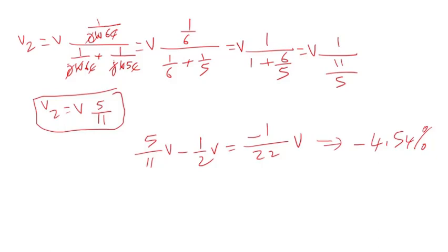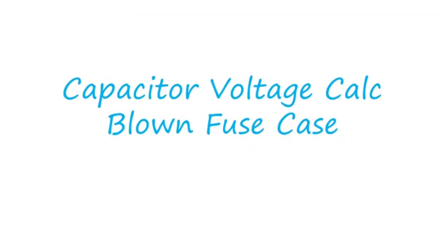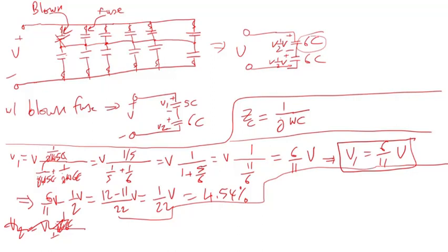So that's very important. Whenever a fuse is blown, you want to balance that voltage. So probably you want to remove, probably open this side here to balance that voltage.